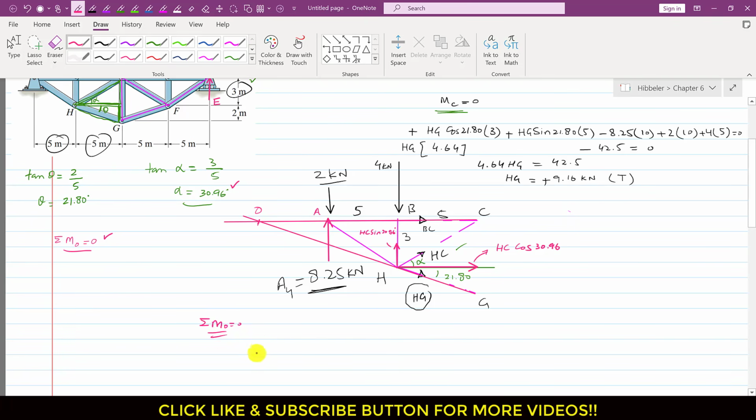So this sine component, HC sine of 30.96, is producing the counterclockwise moment, so I have to write plus, and the perpendicular distance of this sine component from that point O is this length OA plus AB, right? Let me write that the whole distance is OB, and OB is equal to the summation of OA plus AB.